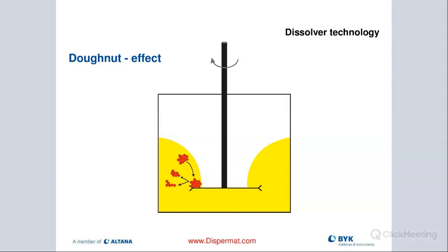If you're dealing with really low viscosity, sometimes it's more difficult to get a donut because the donut would collapse immediately when it gets formed because the viscosity is so low. And here you can see the breakup of these binding forces is really happening at the edges of the blade. And actually on this graph right here, I would have added that same on the bottom because we are also achieving the particle breakup of the binding forces on the bottom of our blade as well.